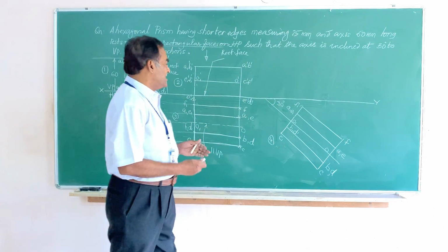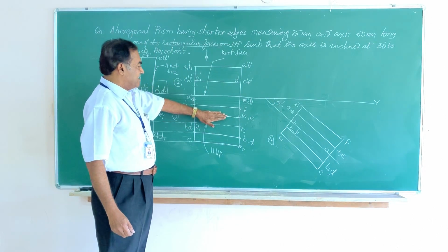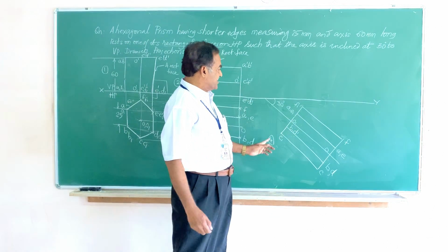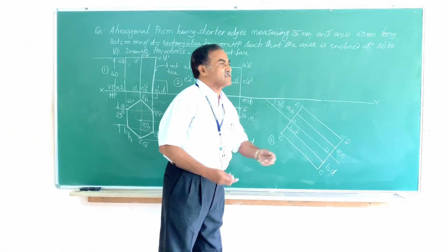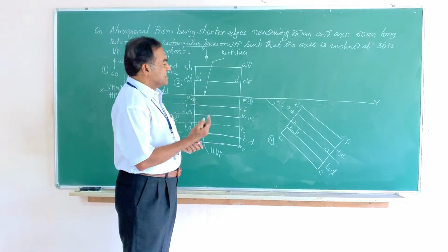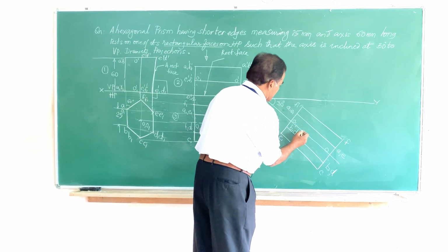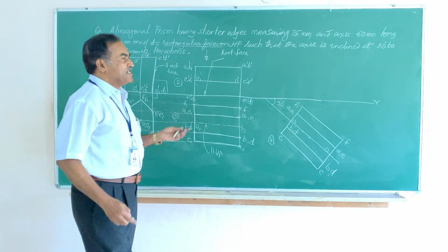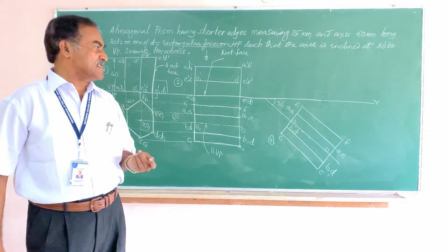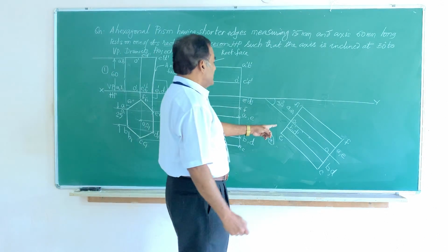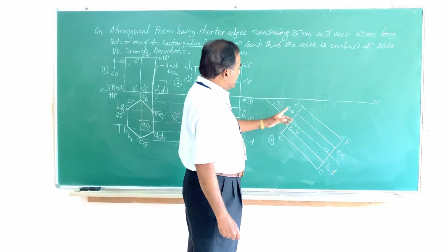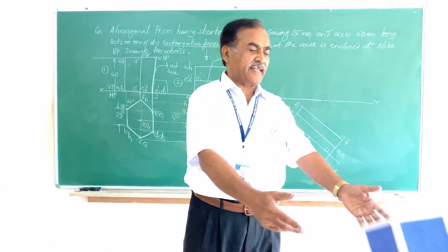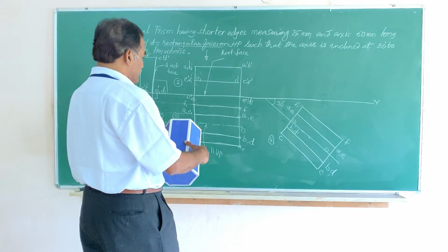So you can see the change. What you had at the top is written here as figure number 4 with the axis of the solid inclined at 30 degrees to VP. You can show it as dash dot, etc. Now, the important thing you observe here is the object is placed such that the axis of the solid is at an angle of 30 degrees to VP.